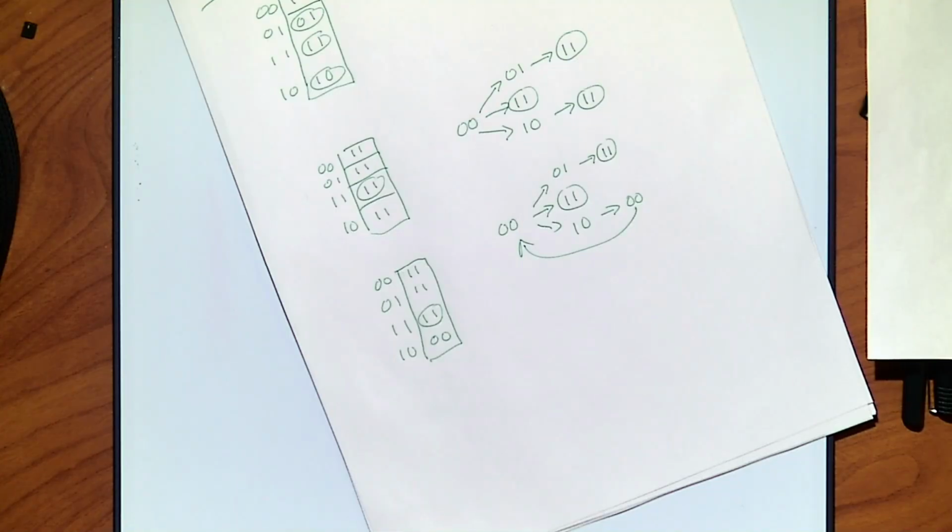Yes, we need to remove critical races. We could remove all of them if we want to, and it won't hurt you to remove all, but you could end up with an overly big system. But if it's a critical race, I don't want that. That's dangerous behavior. You have to remove those. Fair enough? Other than this, it's just like the design you've dealt with.